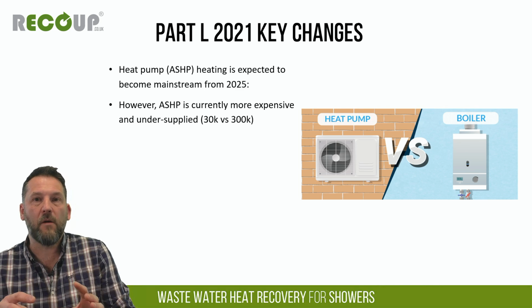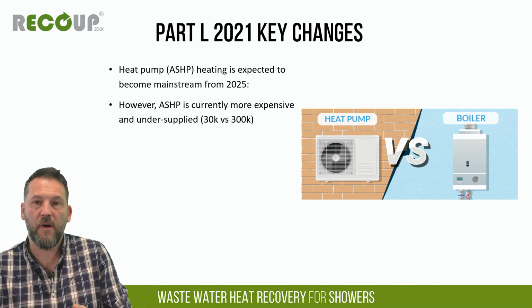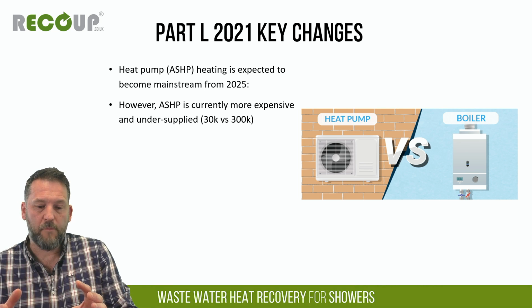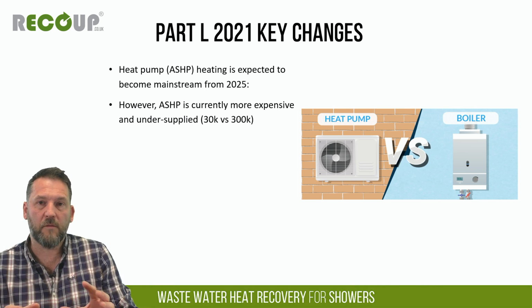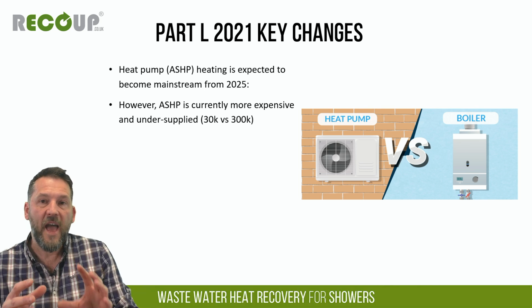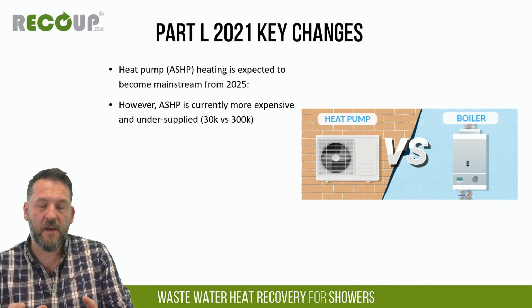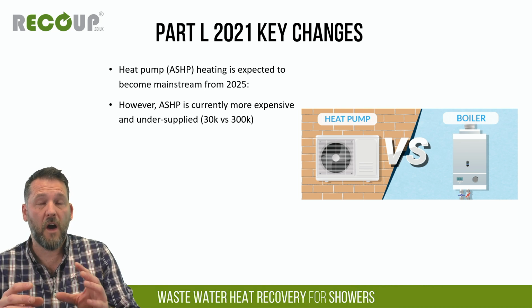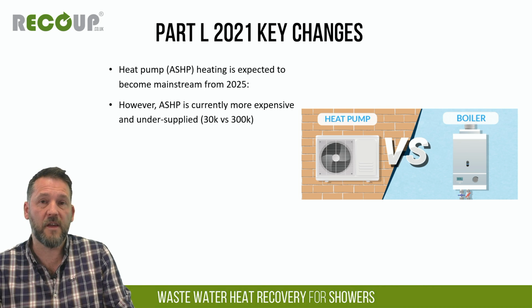Now the current regulations do allow for air source heat pumps. Obviously air source heat pumps are getting a lot of press at the moment for some good, some bad reasons. Air source is a fantastic technology, and certainly under the current regulations, if you were to pretty much just bolt an air source heat pump on to an existing home with slightly increased fabric to meet the FEES, you're going to get a SAP pass.